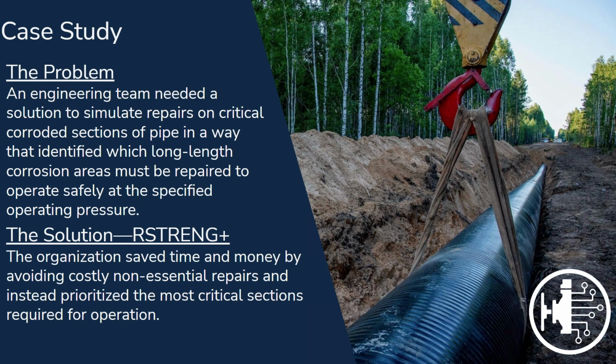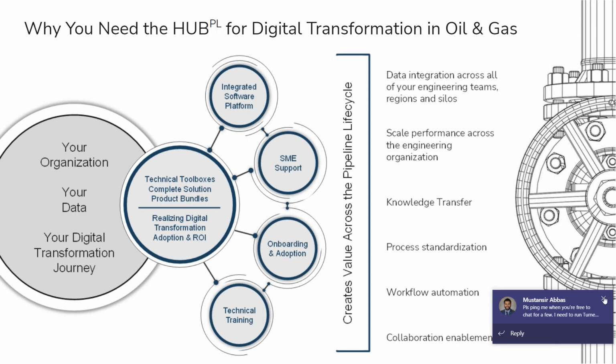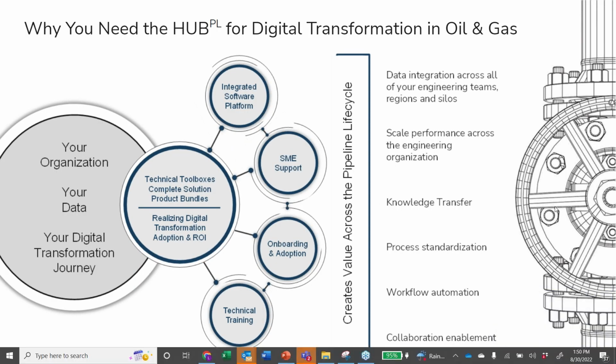When you're involved in digs, you should have pressure tested pipe in case it's required to do a cutout. All this should be done in preparation before you even start, so you don't have some of the problems you need to think about. And where does that go back to? That goes back to having a system that you can use to determine what's going on.